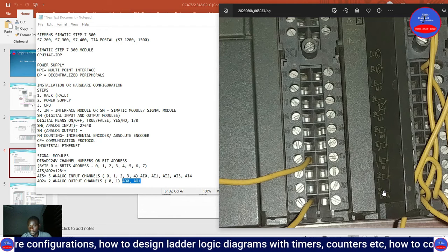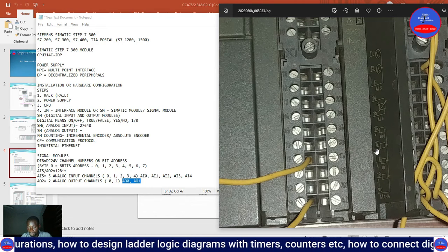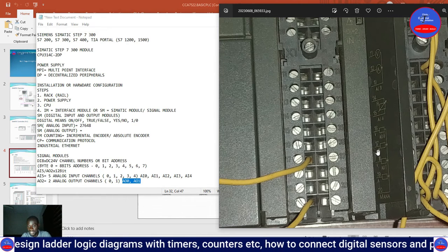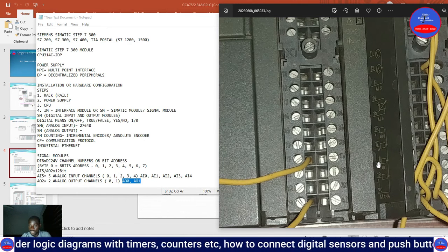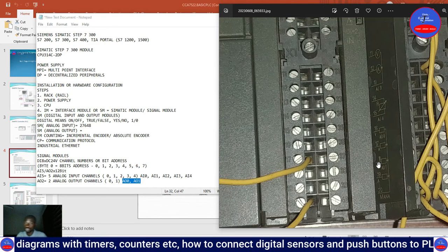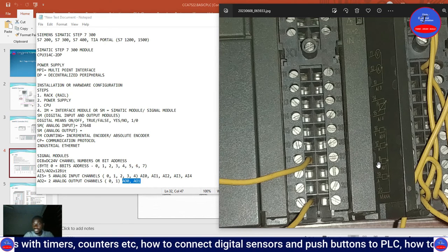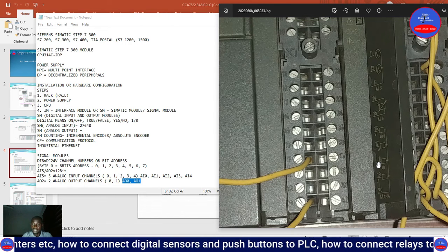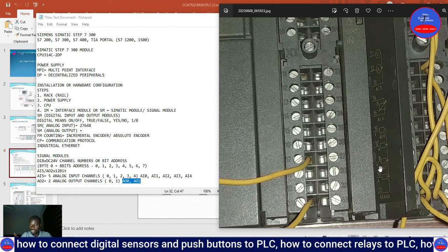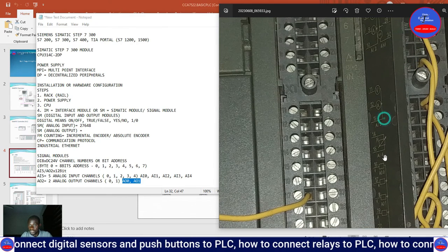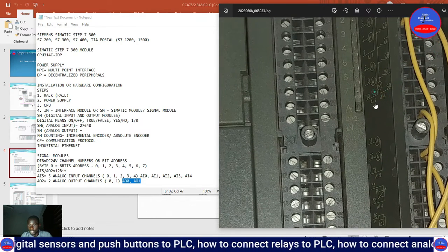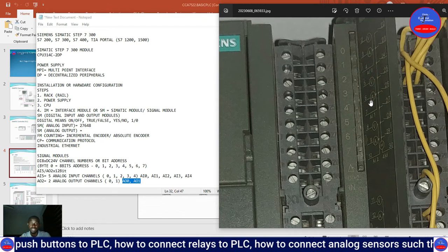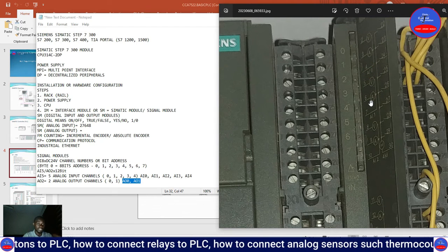These ones will go to the device. This analog output is where you control the speed of a variable frequency drive, and where you open a valve. This one is going to a device, but the analog input is an input signal coming from a temperature sensor or pressure transmitter.